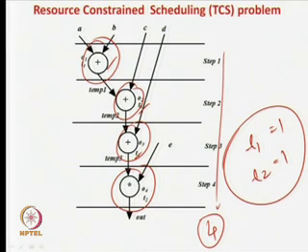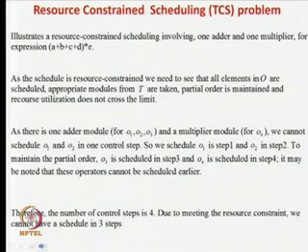If you remember the last example, if our constraint was that the adder count is 2, then we could have shifted this guy over here, then this thing would be shifted here and this thing shifted here, and then your time requirement would be 3. So, now because you have given a severe resource constraint, your time steps have increased. Okay, that is what I have discussed for the resource constraint scheduling problem.